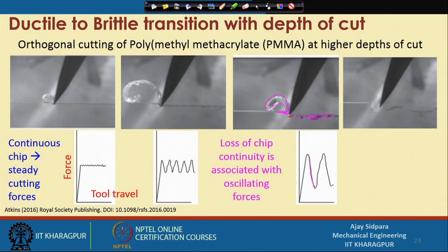So, when the tool reaches that location, it does not require so much force. So, it removes this much amount of material. Now again the fresh material is coming, so again you need a very large amount of force, and that large force is again coupled with the loose material. So, you are getting a very high fluctuation during this cutting at a high depth of cut.